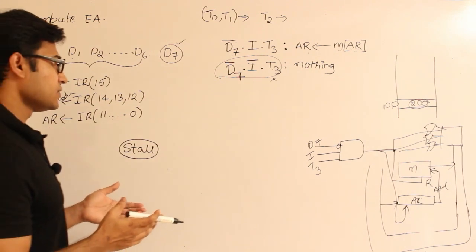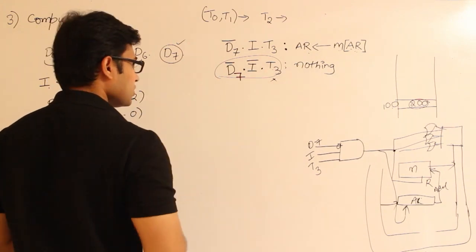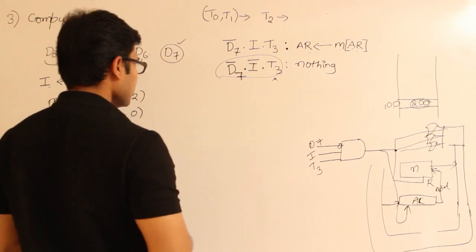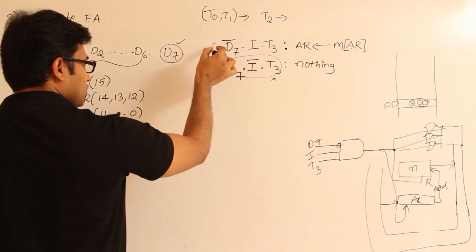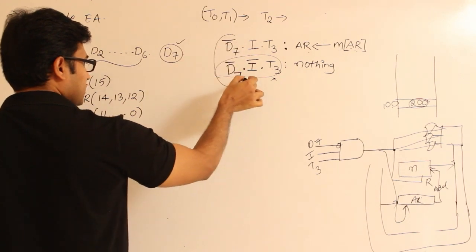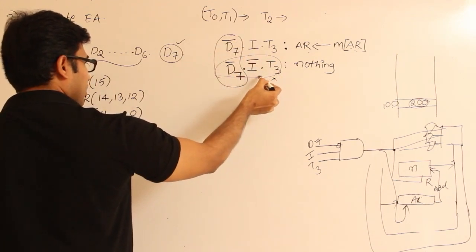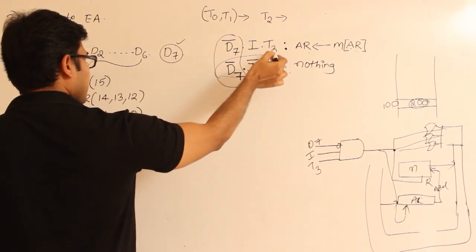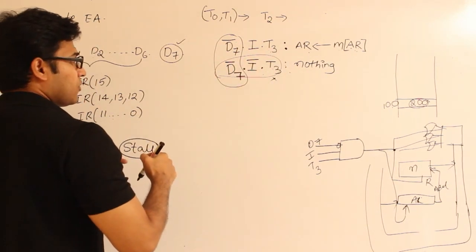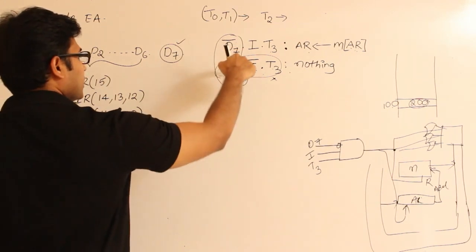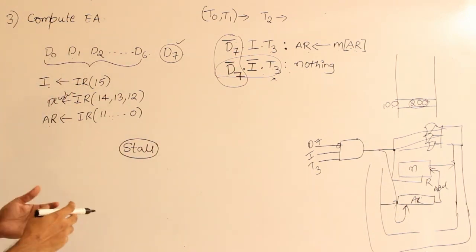There are actually two strategies here. Instead of leaving it, you could directly go on to the next phase, the execution phase, but I intentionally leave it. The reason is simple. These two types are actually the same instructions, memory reference instructions. If I start execution here for one type, and for the other type I start executing at T4, then I have to have two different hardware for both types of instructions separately, even though the action is same. We might end up doing more work.